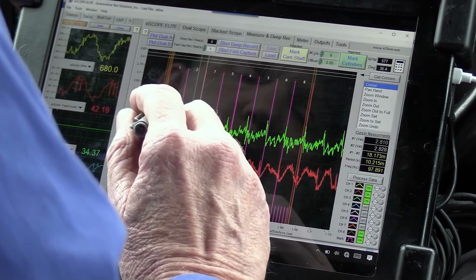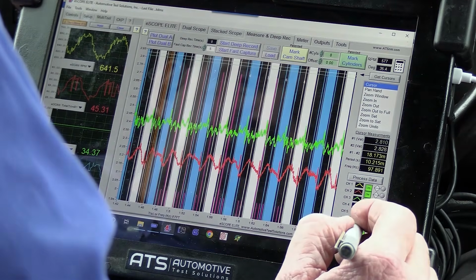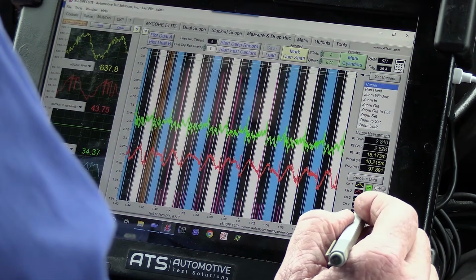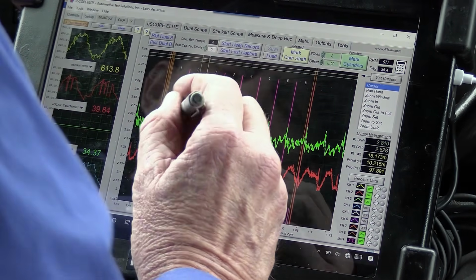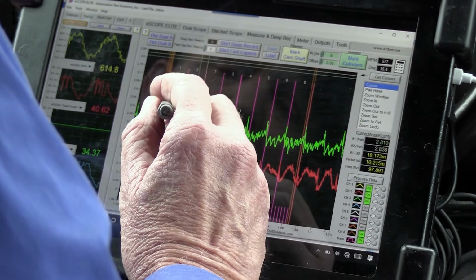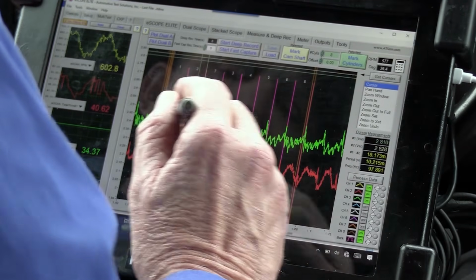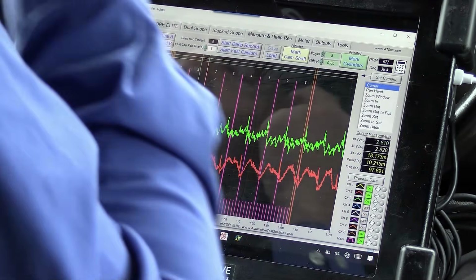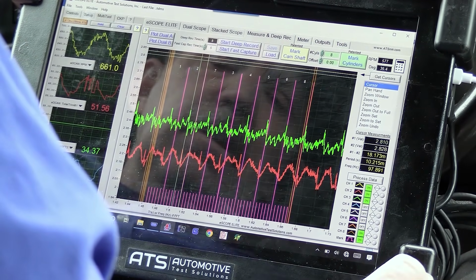Well, that's not coming from the drive changing. The computer commands are not changing. They're all the same. It's just trying to make more pressure there. So this piston in the pump is coming up at a different time than it is over here. That's clearly what's going on here. Now, the only way that that could happen is if the jack shaft chain is loose.